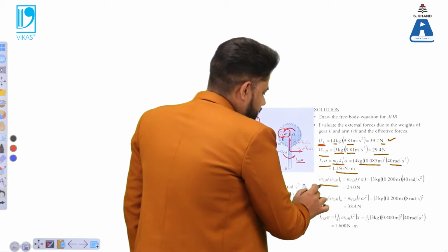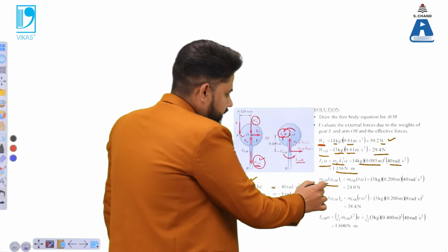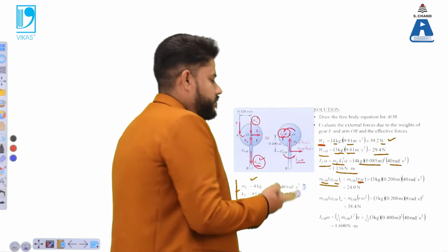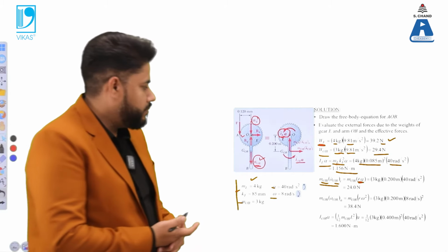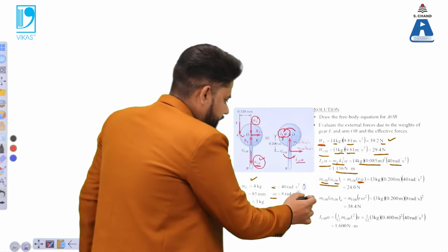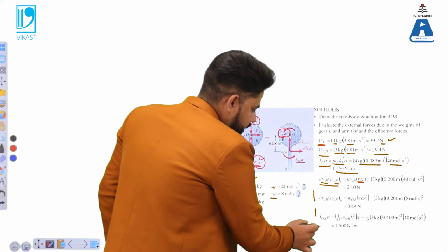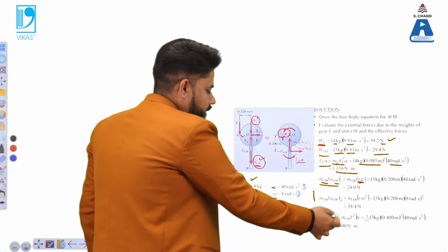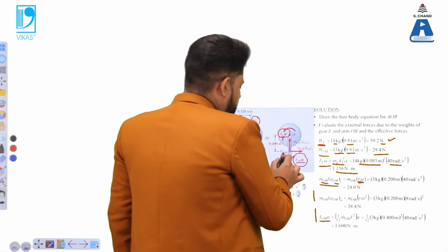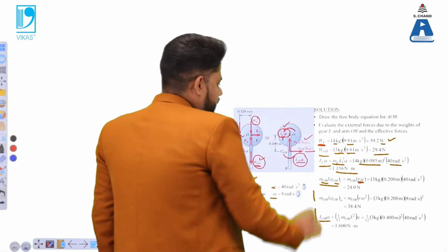And then this movement, which is M mass of OB, and acceleration, which is related to this OB component. So acceleration can be written in terms of that alpha or the angular acceleration component, which is R alpha. So we can substitute those values and calculate MOB in tangential direction and in the normal direction, and additionally IOB into alpha can also be obtained. So we got IOB alpha, we got IE into alpha, and this MOB into tangential component and the normal component.